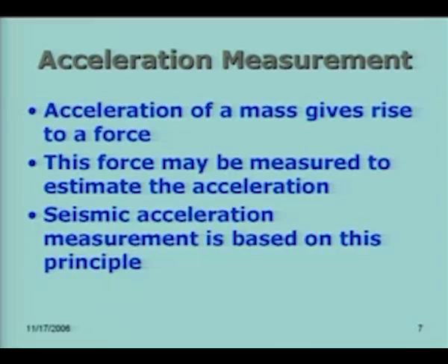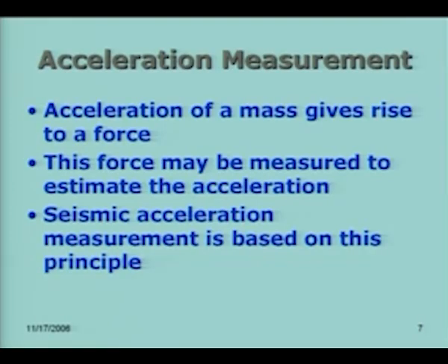We are interested in measuring acceleration, and a meter measuring the acceleration of a member or a mass is called an accelerometer. The acceleration may be due to vibration of a machine, for example, and we would like to measure the acceleration because of the vibration. Or if we have an instrument, we would like to find out how much vibration it can withstand, that is, what acceleration it is subjected to during these vibrations.